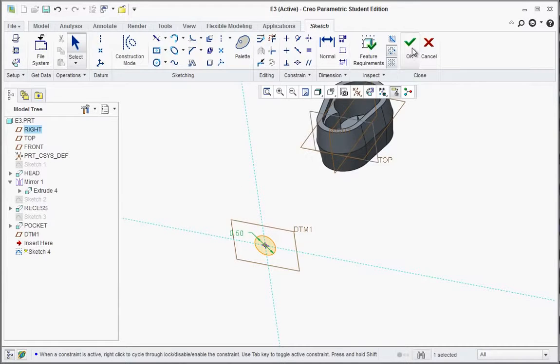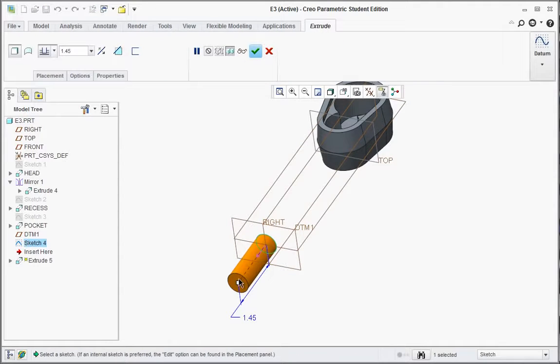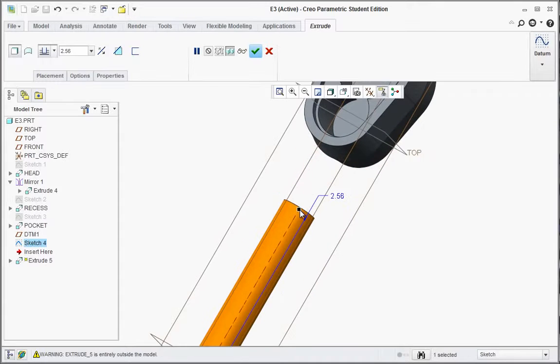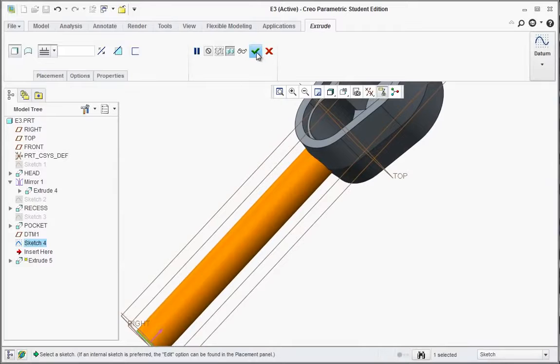At this point, we just hit OK, extrude, reverse the direction up there, but this might be a harder task than we think because we're trying to find the median in between there where it doesn't intersect the cavity that's in that hole. Let's take a look at our tools over here on the upper left and see what we have. In this case, there's an extend up to next surface. Click on that and then hit apply.